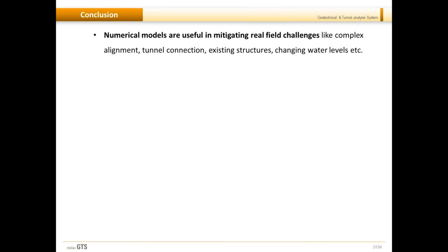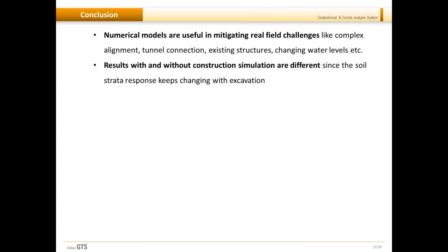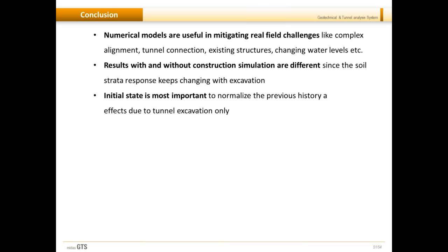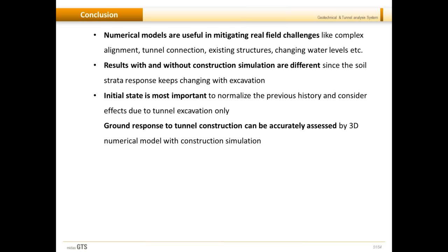So this brings us to the final part of the presentation, where I will be concluding the things that we have learned so far. So first of all, numerical analyses are useful in mitigating real field challenges like complex tunnel alignment, tunnel connections, existing structures, and changing water levels. The results with and without construction stages simulated are different, since the soil strata response keeps changing with excavation. Initial state is most important to normalize the previous history and consider the effect due to tunnel excavation only.